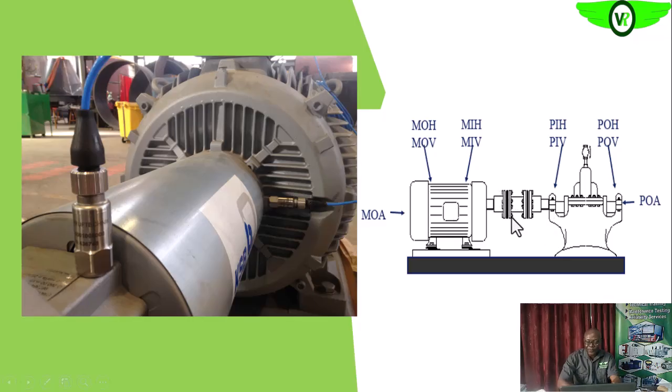So if this coupling is shielded, as we have in this case, it means that we can also do the axial direction without any safety implication. So we have for the pump also, the inboard vertical is the same orientation, then outboard horizontal, outboard vertical and outboard axial.